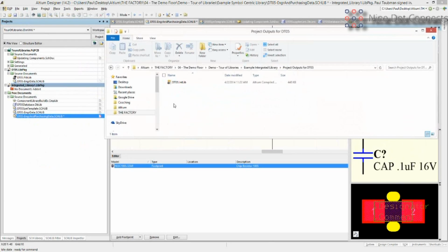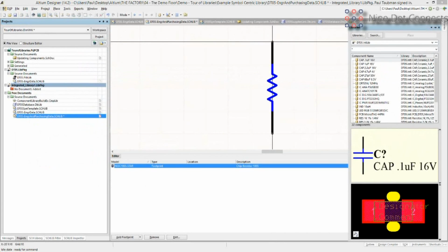And then if you save it, it would actually create another directory, and you start digging a hole here pretty quick every time you take the last IntLib and try to edit it there. So that's what it's for. I think it's a pretty useful little feature, but again, I look at it more as an end product library than a development type of thing. So just for your knowledge as to the integrated library.